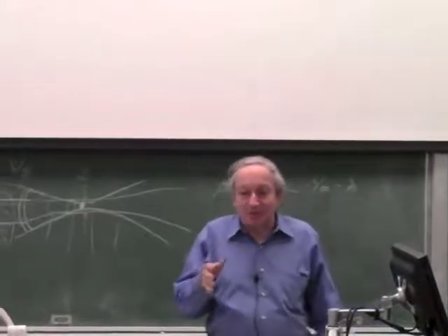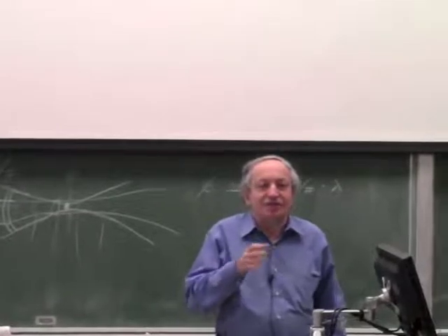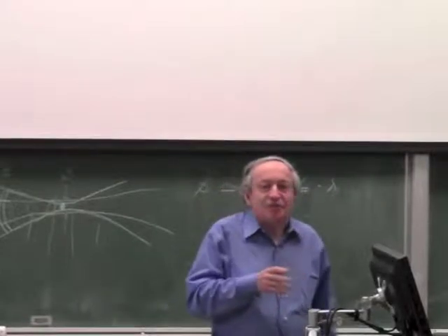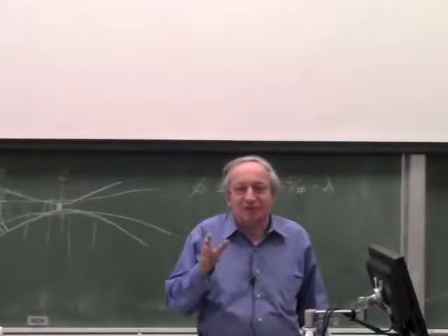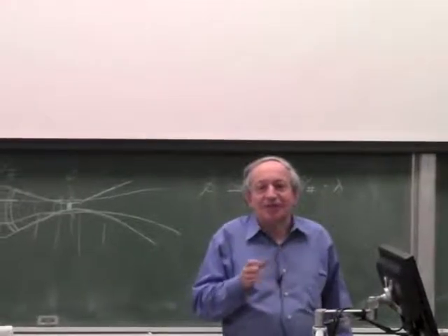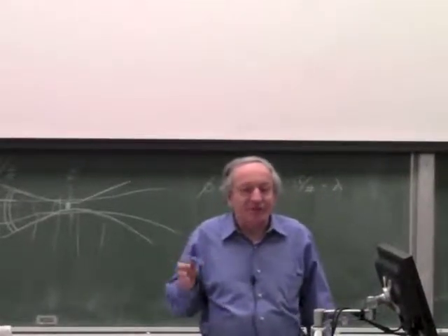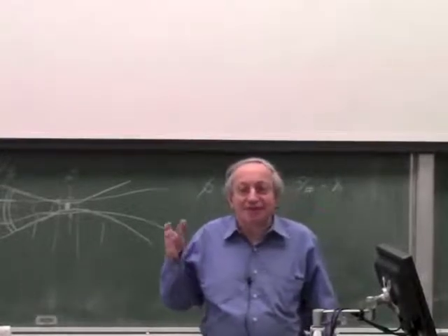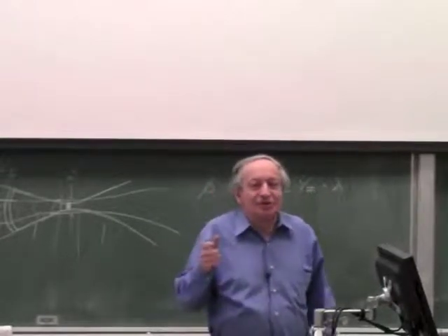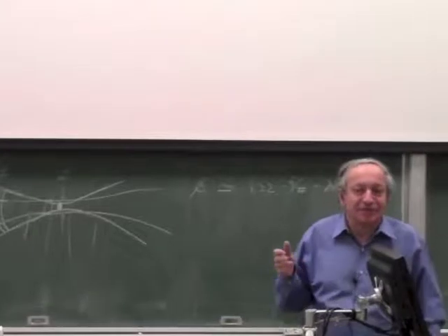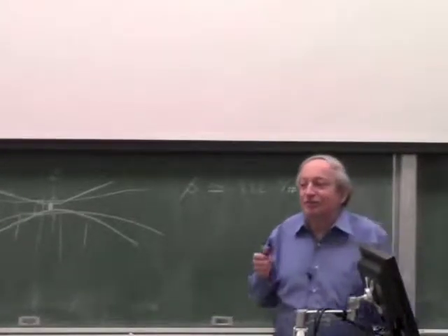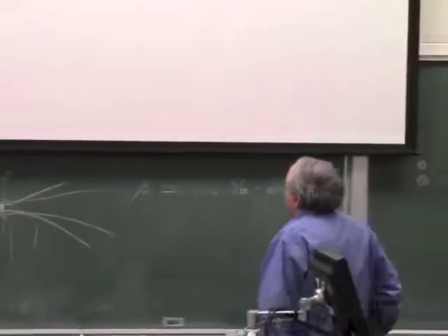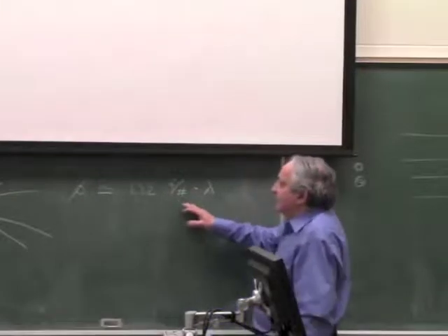If you look at the history of chip making, they started off with 365 nanometer in the old machines, steppers, and then they went to 248 nanometer, which is already invisible UV, and then to 193 nanometer, which is deep UV, and now they're trying to go to 13 nanometer, which is a huge hassle, because there are no materials which transmit that wavelength. Everything has to be done with reflections. But the reason you have to move to shorter and shorter wavelengths is to decrease this diffraction limit. So roughly the diameter you can get to is this.